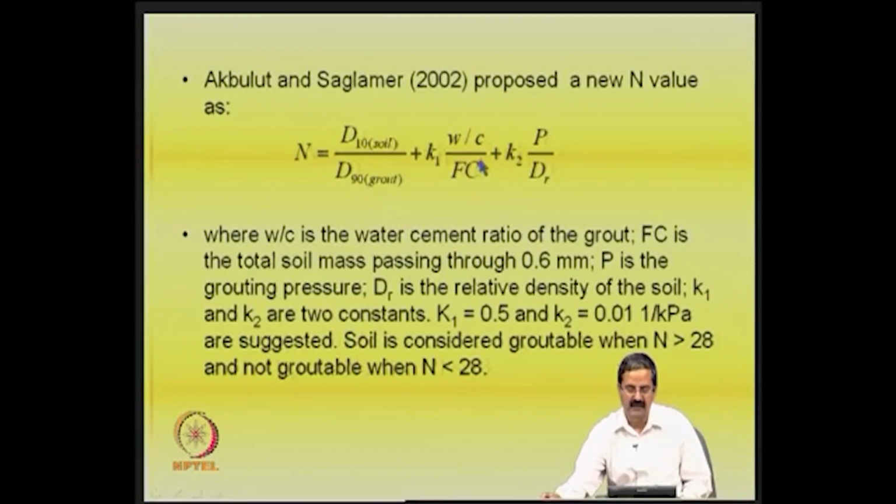It will not take care of the water cement ratio of the cement, it will also not take care of the fines content, grouting pressure and the relative density of the soil. So, these researchers have given some sort of relationship, again it is site specific and empirical, but they recognize the importance of variables like water cement ratio, pressure, relative density and all that,